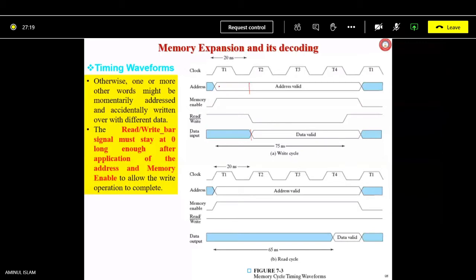This address is going to be sent to the select line through the decoder, and that address is going to make one of the word lines, say WL1, active. I have shown this kind of thing with the decoder earlier. Yes or no? Yes, sir. So one of the lines will be high. That is the select line, which we have discussed.